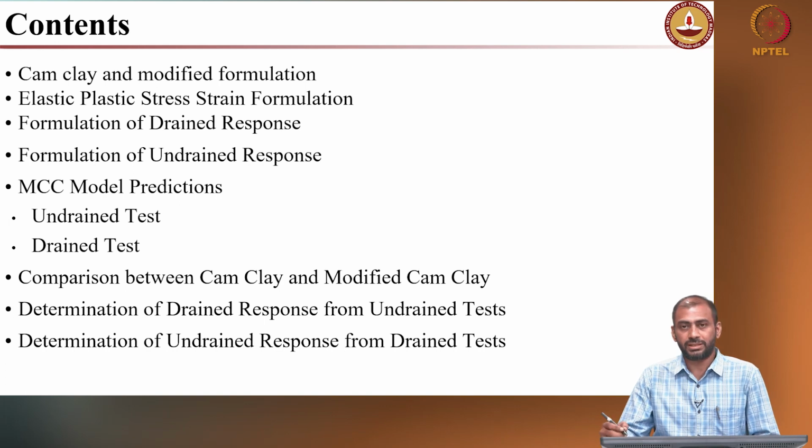Followed by that, we will see the drained and undrained response predictions. Using these models, we will see how to predict the stress-strain response: how the models predict the volume change, pore pressure, and stress-strain response, and a comparison between the modified Cam-clay and original Cam-clay will also be done. Finally, if you have a drained response, how to predict the undrained response, and if you have an undrained response, how to predict the drained response using these Cam-clay based models will be detailed.